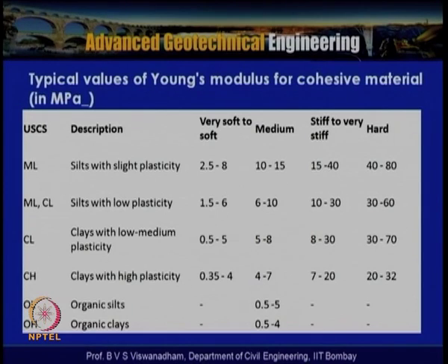So in this particular lecture we tried to understand the octahedral plane and octahedral shear stresses, and based on that three failure criteria, namely von Mises, Tresca and Mohr-Coulomb failure surface. The Mohr-Coulomb failure surface we have seen as a hexagon, and because it has the capability of having different phi angles, different hexagonal cylinders are possible.